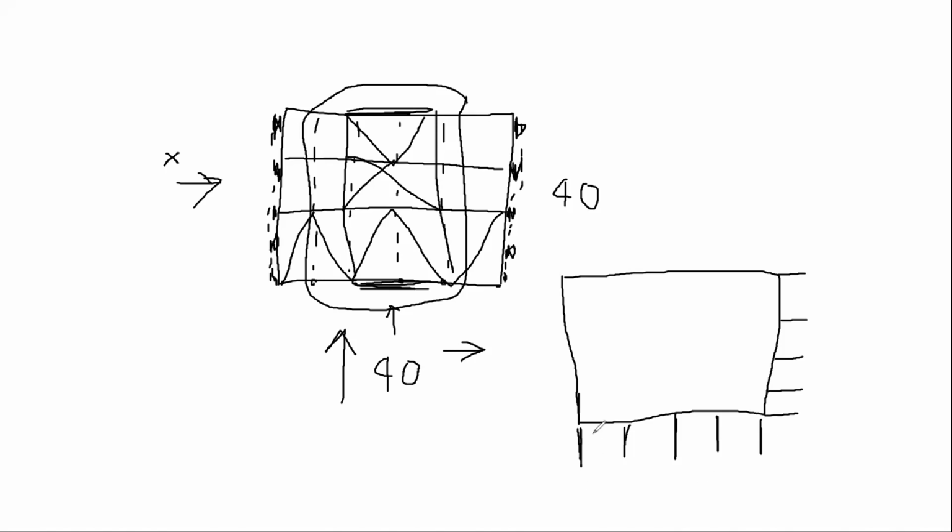Like if your program was for a whole lot of rooms here, well, then this might be a good solution because you need walls anyway. And so if you had shear walls like that, we would have to put in horizontal ties in the roof to transfer the inertia forces back into these shear walls.